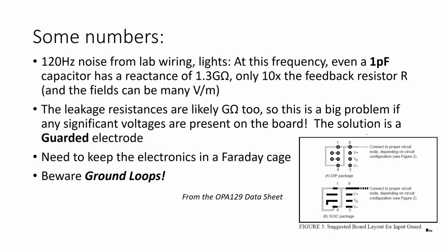And then if you have a printed circuit trace that, say, has less than 1/10 of an ohm of resistance, but you transiently get an amp of current in it, that would be less than 1/10 of a volt, which if you're measuring a millivolt would absolutely kill you. So this situation is called a ground loop. They're very common, and so you want to keep signal circuitry well isolated from power circuitry.